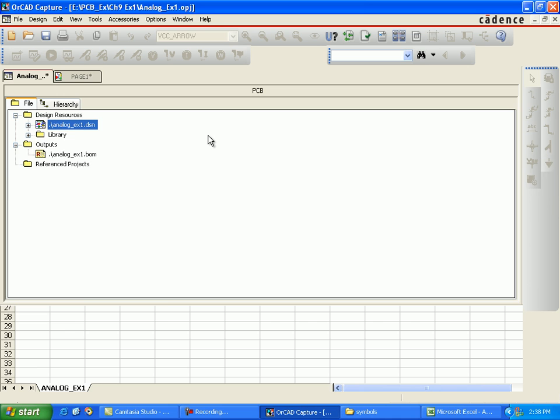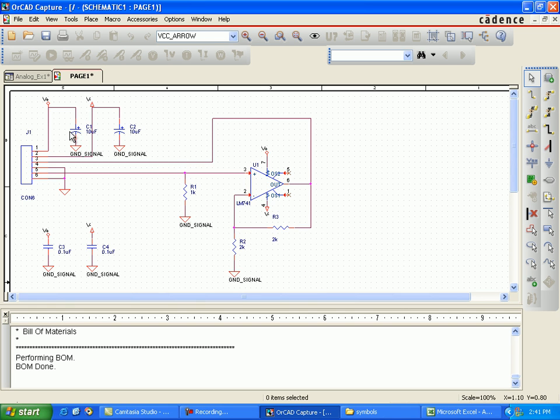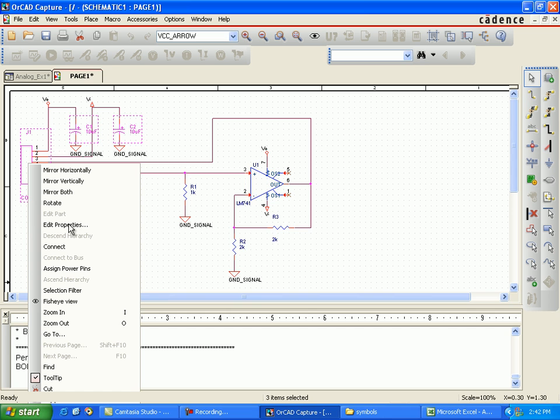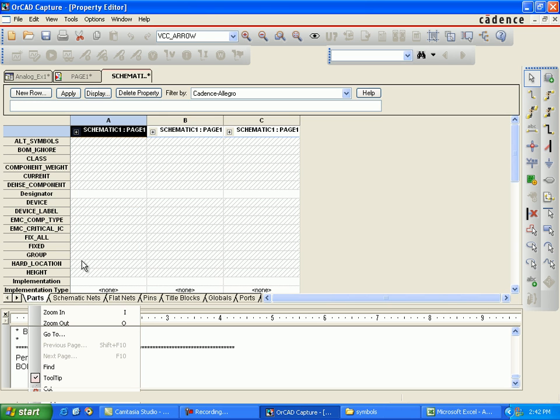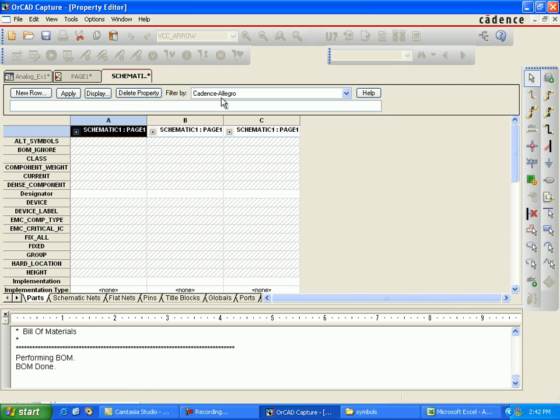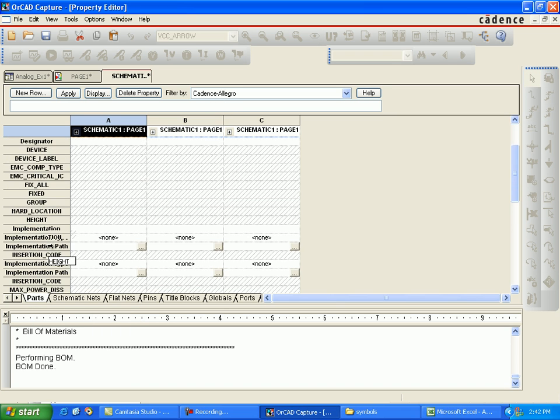Make sure you have all footprints. Yep, we have all footprints in the bill of material. This is needed because when you go to the vendor for the component, he asks for the footprints, how you want it: axial, radial, ceramic, surface mount, whatever. If you have these things, you can search for the component in the market of suppliers.